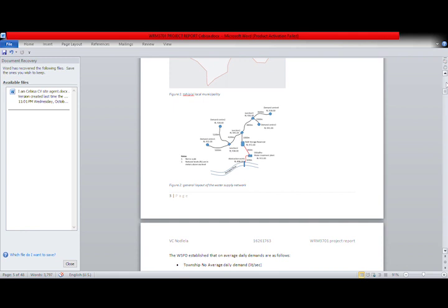There I'm supposed to provide for 4 different townships, as you can see in this overview of the design. There's township 1, township 2, township 3, and township 4, and the water will be supplied from the Nyangwe River, and we will be using the abstraction works as the datum. So all of the levels which have been given in this overall layout will minus that level to get us the reduced level.